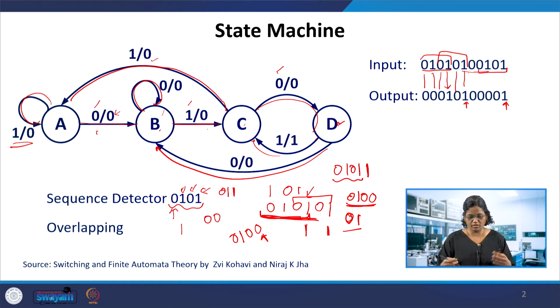You have to make the Verilog module for this, using the state diagram. Use an always block for state memory, like in the previous state machines, and the next state logic, which comprises all these details.